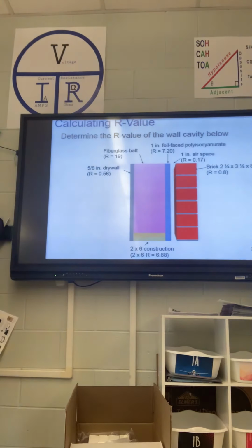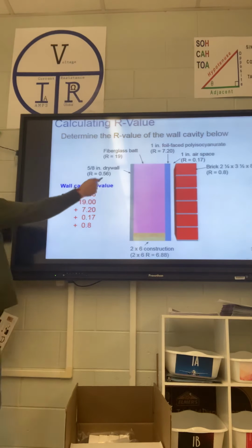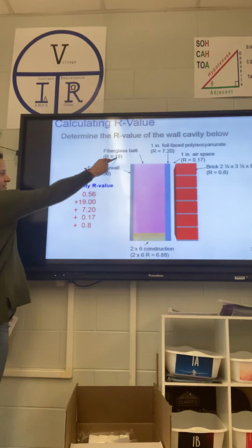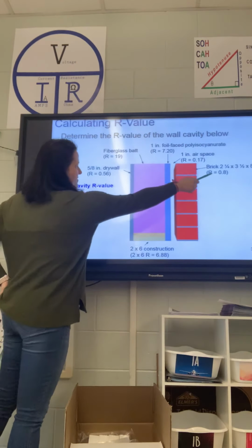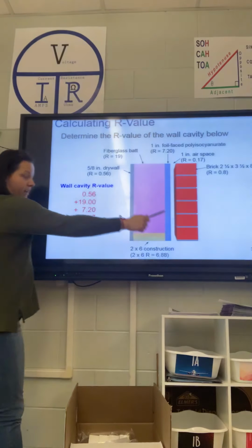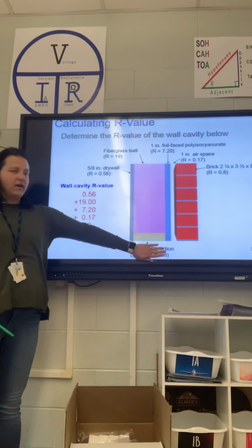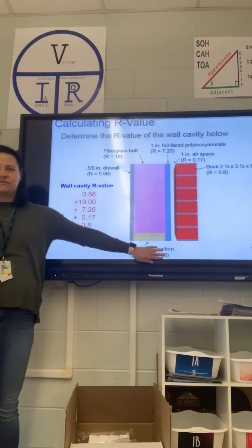So you gotta determine what's the R value. You ready? You add those numbers up. So 0.56 plus 19 plus 7.2 plus 0.17 plus 0.8. Do not include your studs.